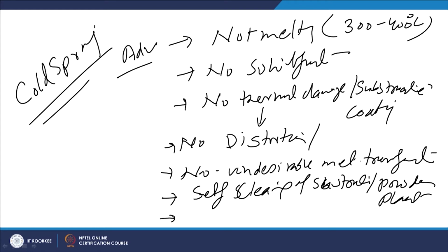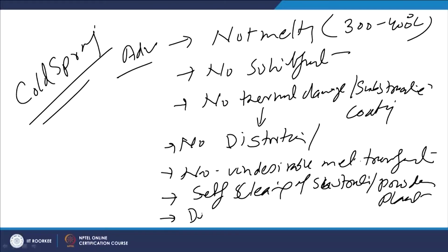At the same time, the requirement of surface preparation like shot blasting, shot peening etc. is also reduced, because impact of the particles at a high velocity results in good mechanical interlocking.